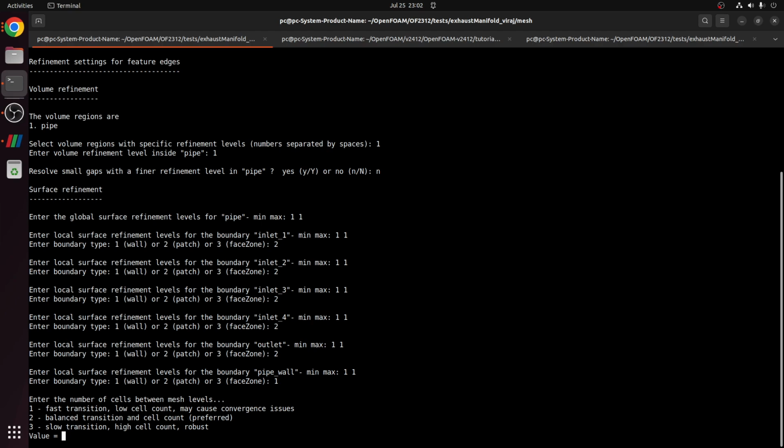So basically, this is a cut cell Cartesian type of mesh. One cube will be level 0. Let's say the next level will result in 8 cells. One cell, if you split it, will be 8 cells, correct? Now, for example, on one surface you can have level 1, whereas in the interior of the geometry maybe you will have level 0. Not only wall, I'm saying any place you can have a very fine refinement level.